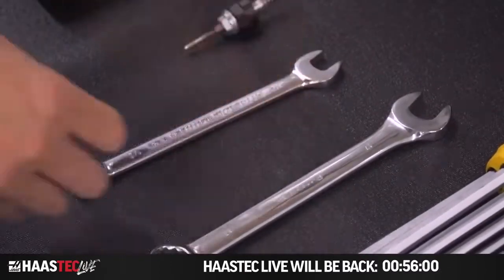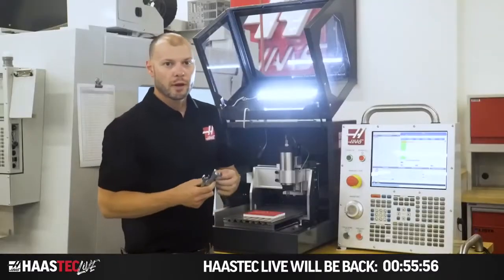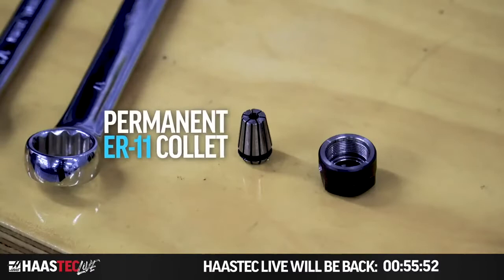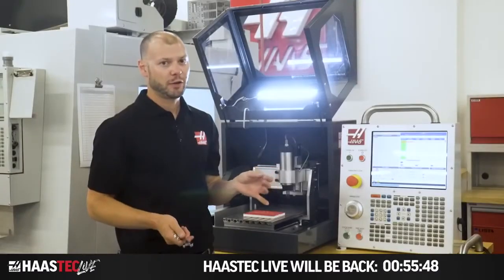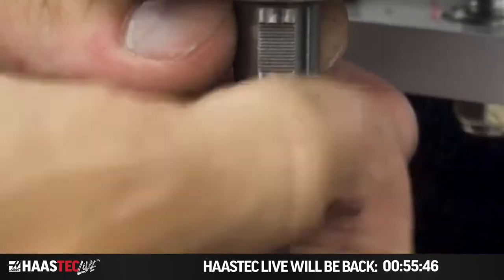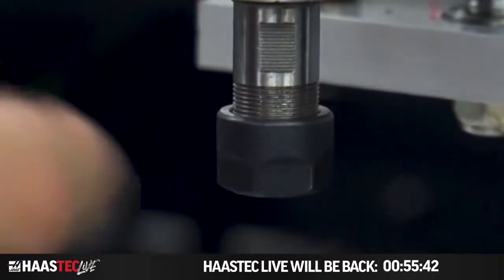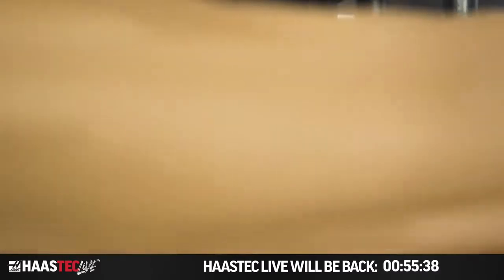So, I have my 1/8 inch 3-flute end mill, and I'll tighten this in the spindle. I should mention the spindle has a permanent female ER11 collet interface for the spindle nose, so you'll need a set of ER11 collets for each machine. Now, I'll tighten my tool in the spindle. It's a small tool, so don't over-tighten it.